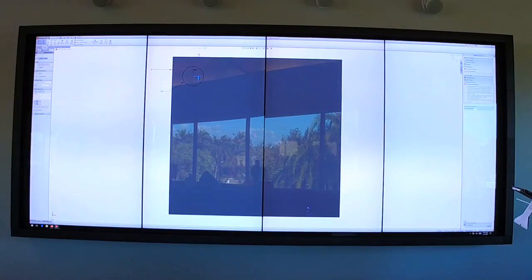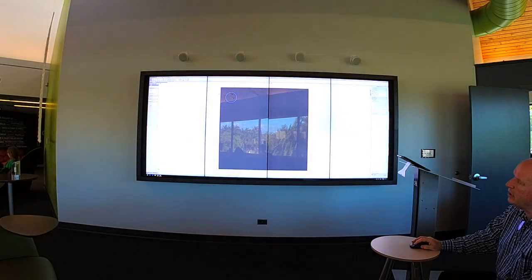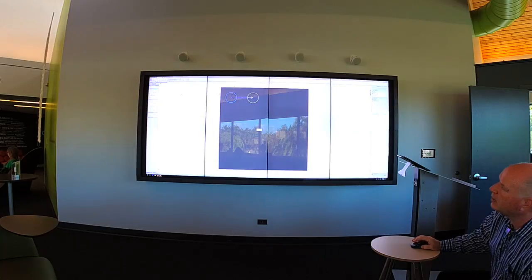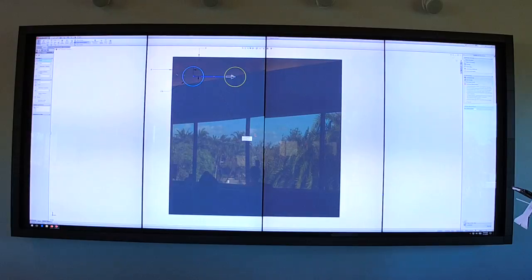Now, I could do the same for all 4 corners, but I don't really want to do that. So why don't I replicate the holes? Why don't I make them? So if I highlight, just take the smart dimension off. If I highlight this hole now, there's a thing up here called, what do we call that? It's a sketch pattern. So in the pattern right now, it's showing me one extra thing. Now I can add more of those. If I can have 2 or 3, I can come back to the 2.